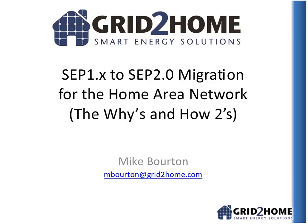Why is this important? Because if we want to avoid brownouts and blackouts in the future, because we don't have the reserve spin to absorb the intermittency of renewable energy, and storage is still expensive in large amounts, we will have to shape the consumption of electricity so that it follows the way the cumulative supply of electricity is available.